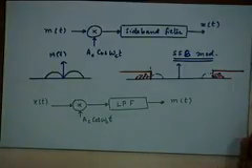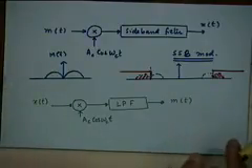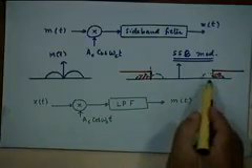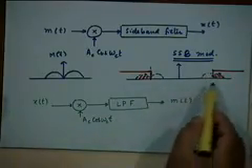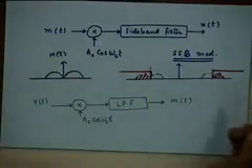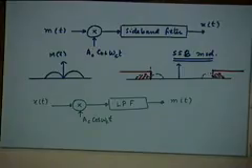It remains the same. Are you all with me? So the demodulator remains exactly the same that we had for DSB-SC. Just apply the frequency translation theorem onto this spectrum, and you can see that your baseband spectrum comes back, along with a component around 2fc, which will of course go.